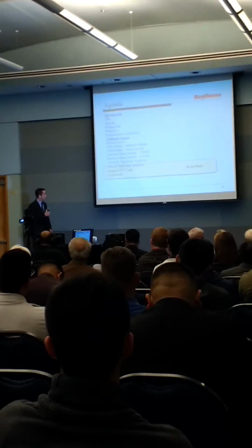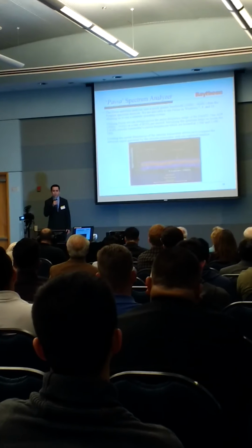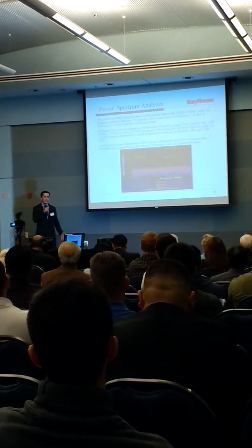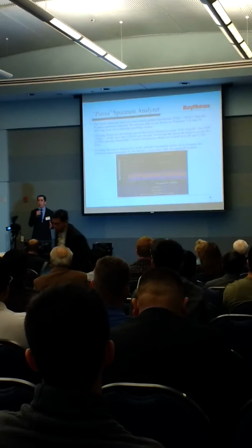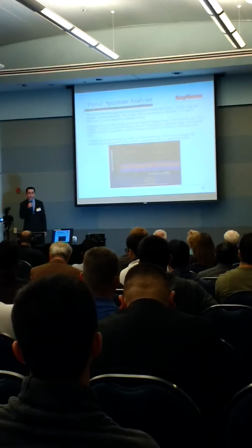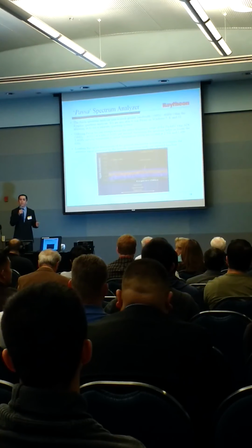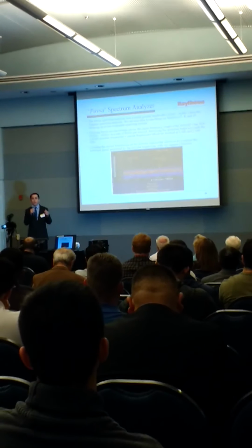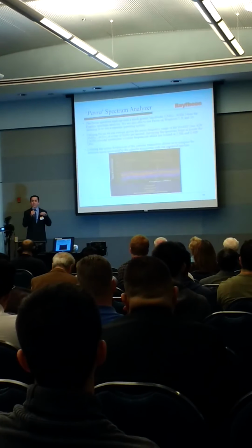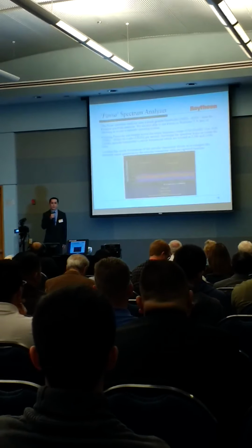Now let's move on to the passive spectrum analyzer. It's important to note it has a much greater bandwidth than the phosphor spectrum analyzer, allowing us to have a greater view of our frequency spectrum. Utilizing the passive spectrum analyzer, we are able to locate the 2.4 gigahertz intruder transmitter's carrier frequencies, which is important because locating these carrier frequencies allows us to feed that information into our software-defined radio alarm system, such that we are able to feed the intrusion signals generated at these carrier frequencies so that our alarm system can then compare it to our baseline capture that we took earlier and set up an alarm whenever there has been an RF intrusion.